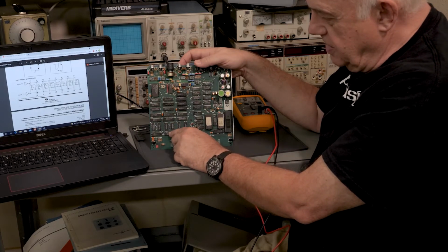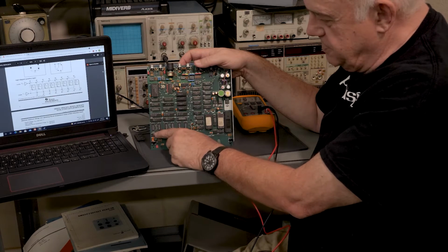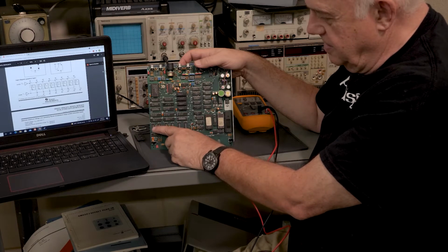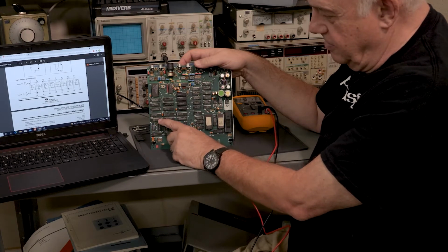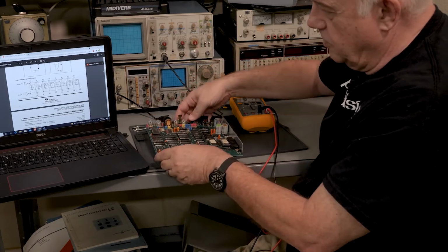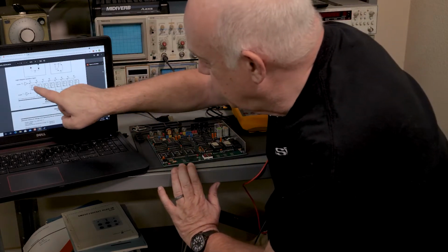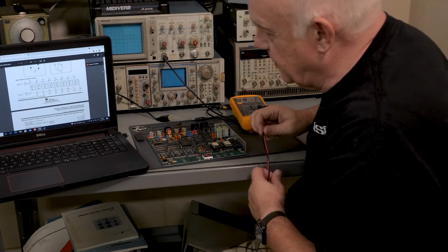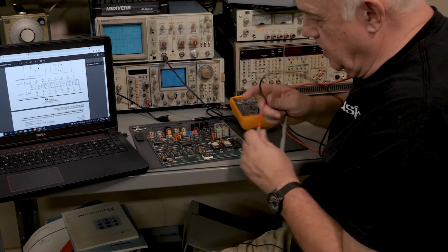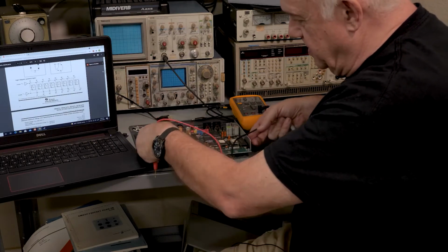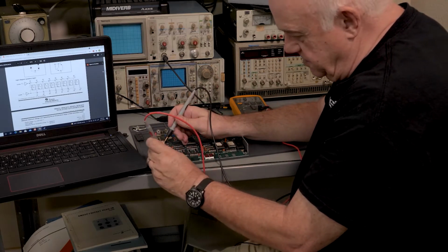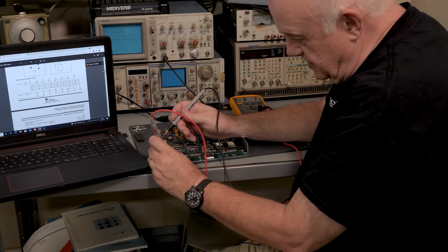All right? So if I'm correct, some outputs of here will go to some inputs over here, and some outputs of the adder are going to come up to here, or maybe to here. We'll find out. So what we're going to do is look at the first data output, which is called Q, which is on pin 2. Because pin 2 is right there, I take my probe, and I'm sorry if you can't see this very well. I don't have an overhead camera because I'm poor and broke.